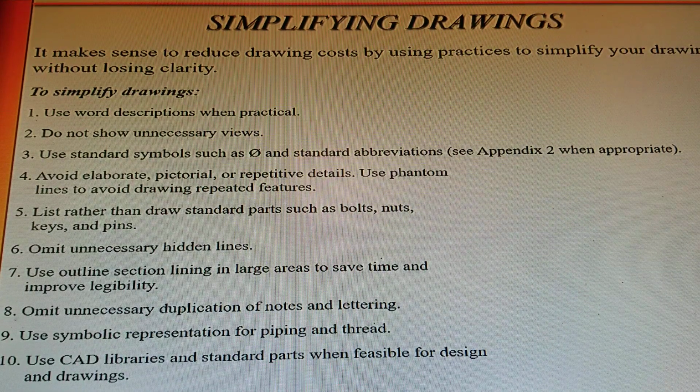Simplifying drawings. It makes sense to reduce drawing costs by using practices to simplify your drawings without losing clarity. Okay, these are 10 suggestions on how to simplify your drawing. Number 1, use word descriptions when practical. Okay, describe it verbally. Number 2, do not show unnecessary views. Do not draw any more than you have to.